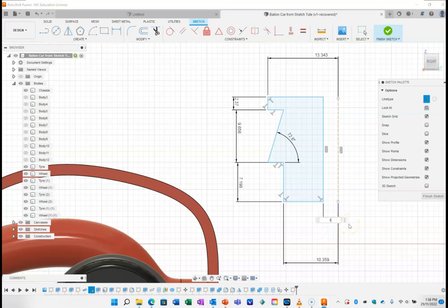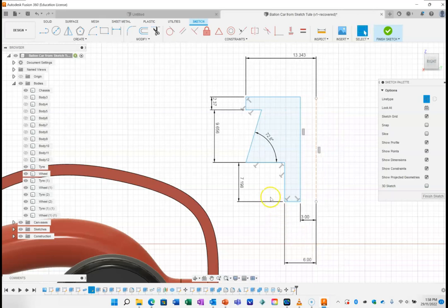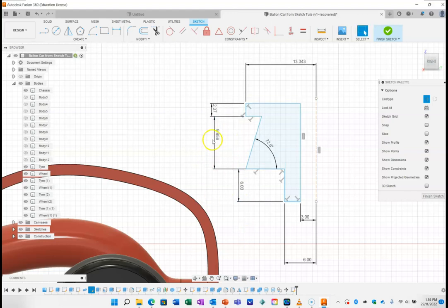So that's going to be a 3 millimeter hole from there to there. This one here is going to be a total of 12 millimeters out. So I'm going to go from there to there is going to be 6. I'm then going to use the dimension of this one here. Remember that was 6. That's my spigot hole depth. That's an important one. I'm going to use this dimension here on my plan. It's going to be 15 millimeters.